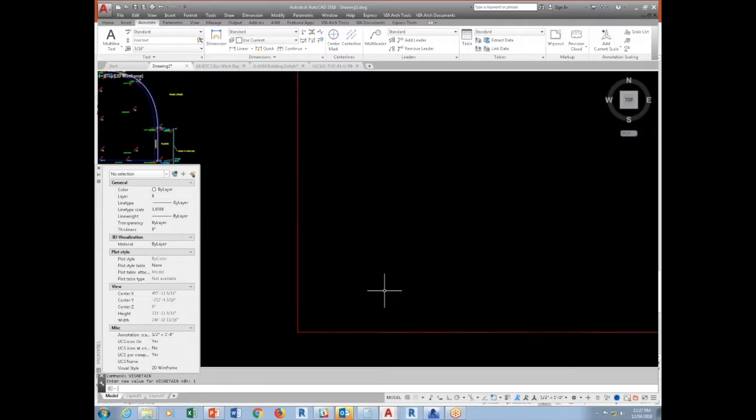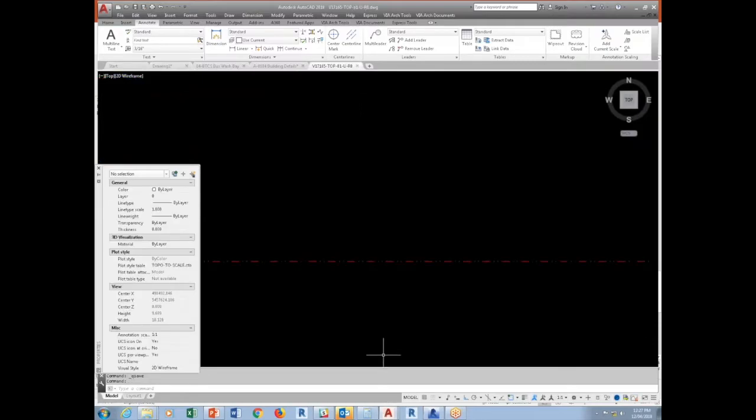Because what happens is that whenever you have layer freeze, let's say for example certain XREF objects or layers you do not want to show, the minute you set it to 0, it's going to reset back to whatever is unhidden or unfrozen in this particular XREF. So it will pick up this particular drawing as its original state. Okay? So normally I don't do it. I always change it back so that you avoid having this kind of messed up on you.